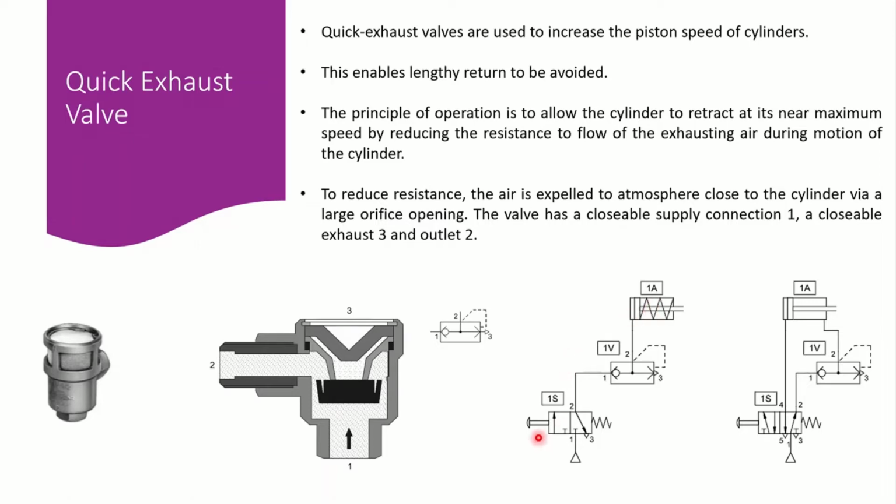If I push this button, the air will be passed, and this ball moves to there. This is going to have the air, but when we have the exhausting, the air comes here, first it pushes this ball to this edge, the air cannot pass, therefore it should exhaust through port number 3 to the atmosphere, right? And here we have the quick exhaust valve on the advancing procedure, which means if the air is coming to the system, we would have again the same functionality in terms of the speed of motion that we expect for this piston.